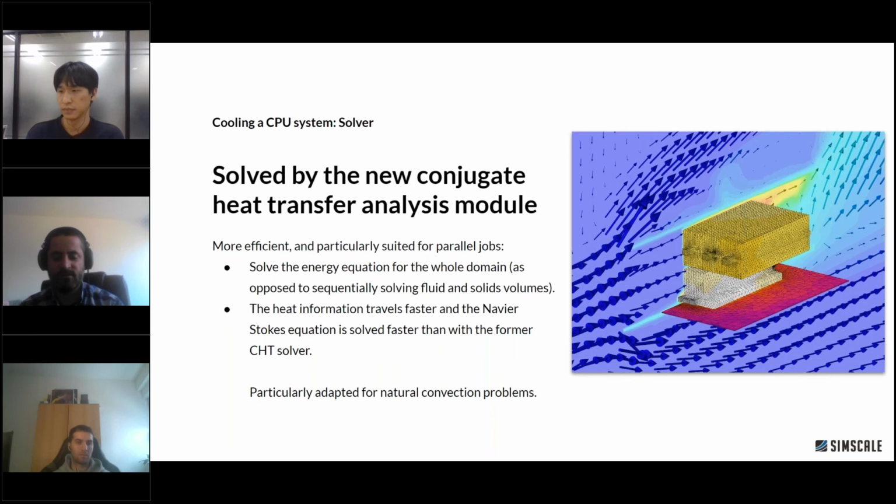And in many cases, we really don't want to estimate, for example, convection coefficients. We really want to see what the actual physics do. How does our convection system work here, and take all mechanisms of heat transfer, conduction, convection, and additionally radiation into account. And that's what we usually do in a so-called conjugate heat transfer analysis.